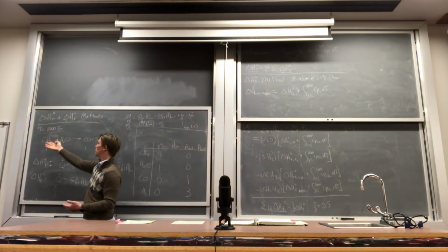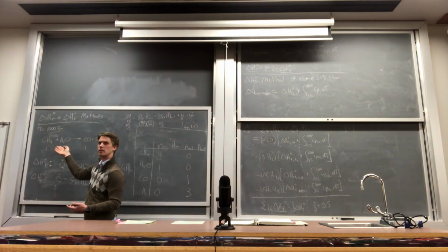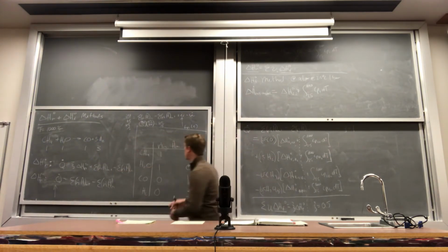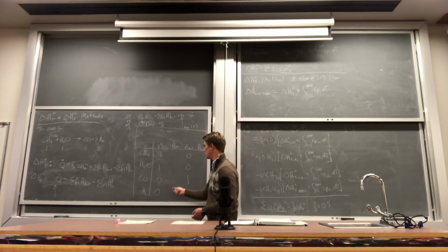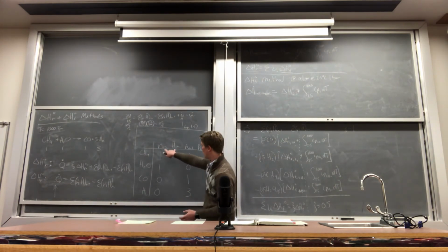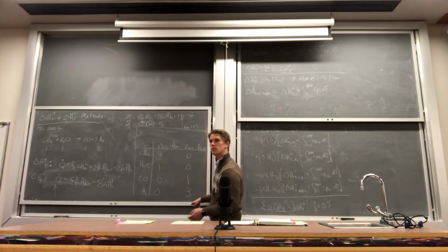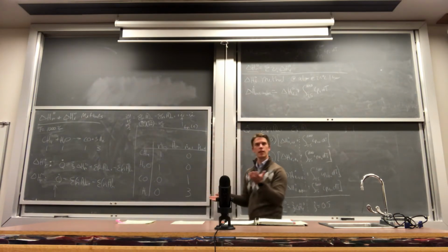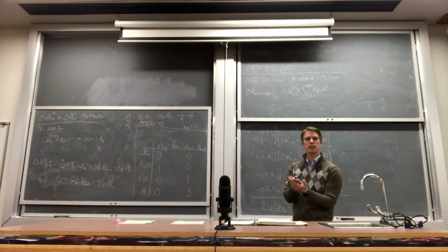This is our outlet temperature for the steam reforming reaction that we did. In that process, we can calculate definitive numbers for every single enthalpy in and enthalpy out for all of our species because we have access to the data tables. Then we add up all these terms. The imbalance of the enthalpy in and the enthalpy out tells us what our heat requirements are.